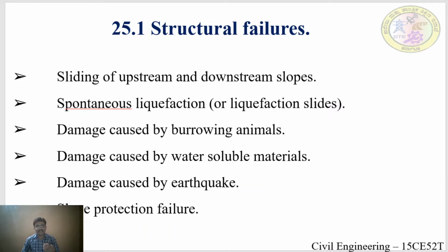Force exerted by the water on the upstream face of the dam. If it is more than the resisting force of the dam, then the sliding will be occurring. That is the structural failure.